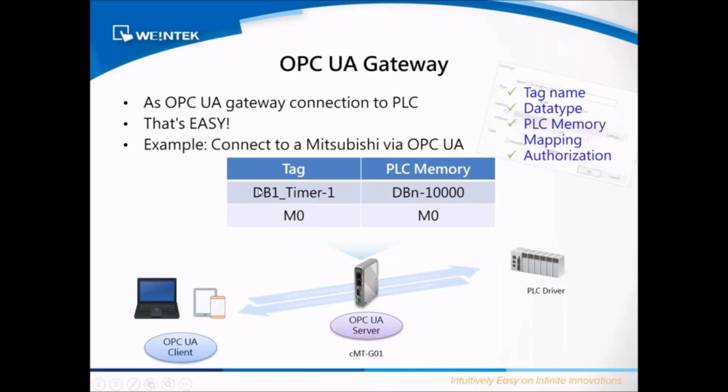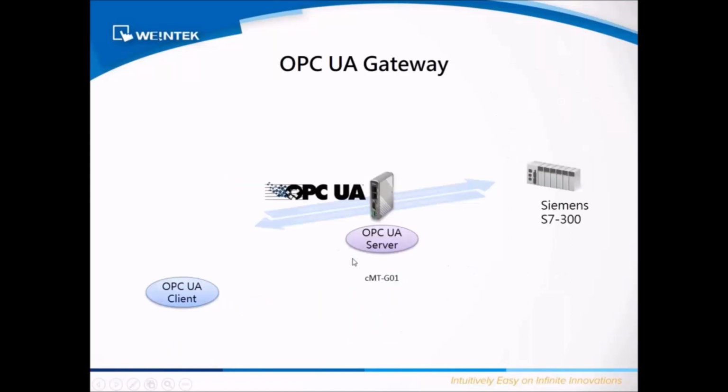So this one is much easier for people to understand what this is and what information to expect inside this register. And what I have right here is I'm going to use one PC client to connect to the OPC UA server, and then retrieve information from the PLC driver. And also I can use an Android phone to access data on the OPC UA server here.